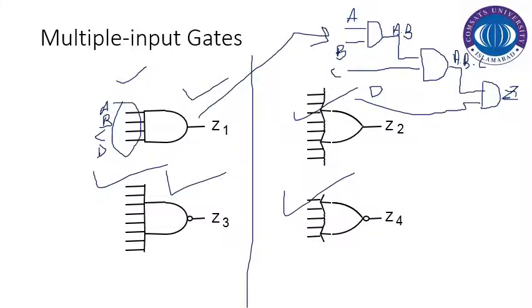Okay, so let us see the economical approach here, and let us assume that one IC contains one specific gate, just for the example. Otherwise we know that the standard ICs can contain four two input gates, and you will learn how many multiple input gates can be carried in a single package when we discuss IC packaging.